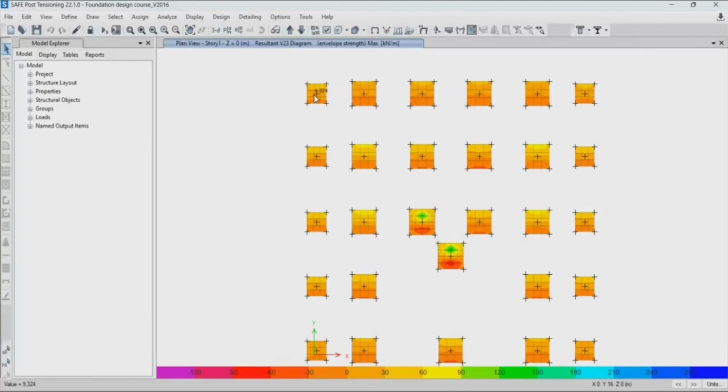Okay, so when you run the design, CSI SAFE is going to ignore your individual mesh and nodes. Instead, it is going to capture all the tiny scattered bending moments inside that strip lane, right? And it is going to integrate across the width of the strip. Okay, so the output is going to give you a combined bending moment, Mu, for that specific lane, which is going to be measured in kilonewton meter.